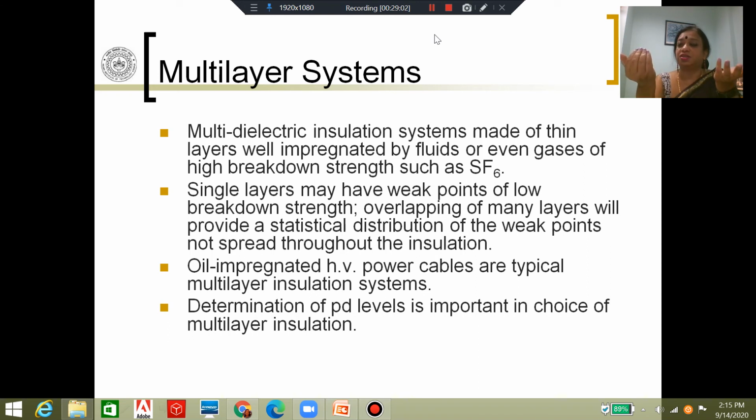Electrons move much faster. They can collide and ionize much faster. But when they are captured by neutral molecules and become negative ions, they do not move as fast and do not have that much colliding ionization capability. So in fact, what an electronegative gas does is remove electrons from the gas, so that the ionization to breakdown process becomes much more difficult.